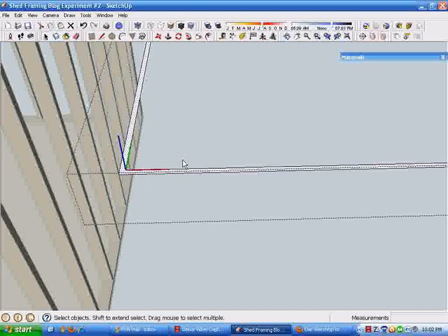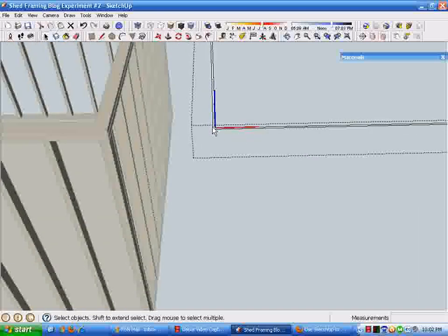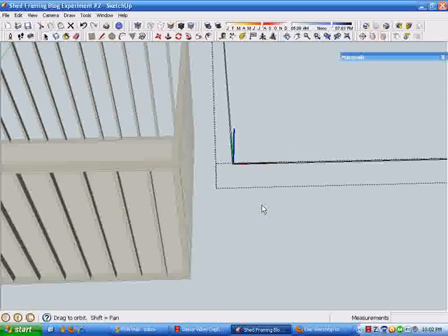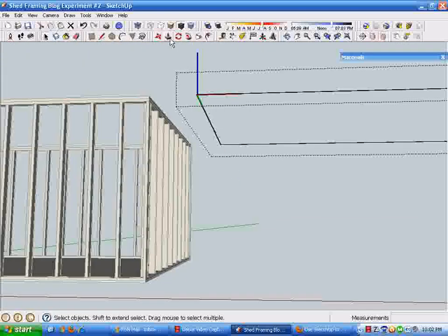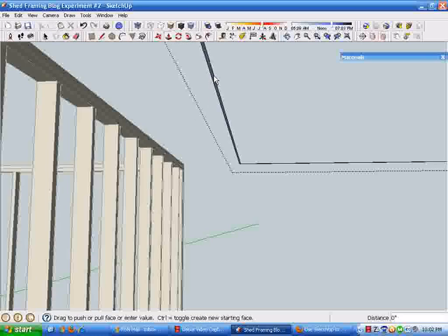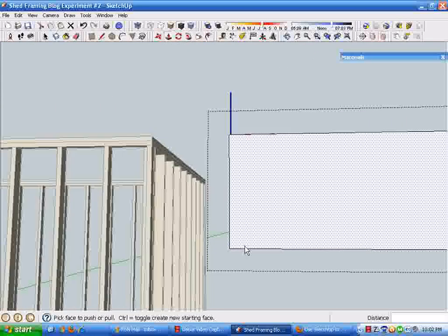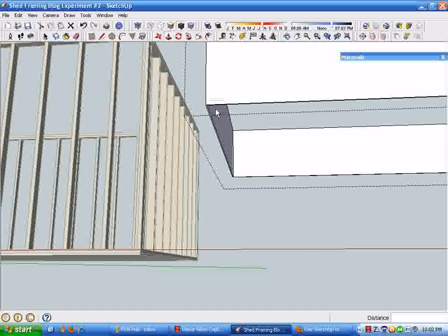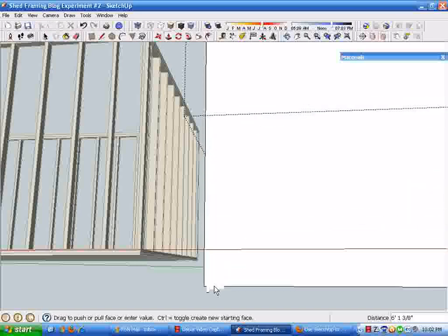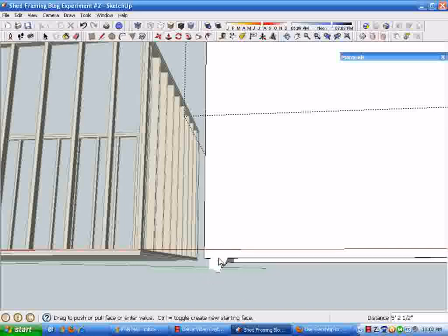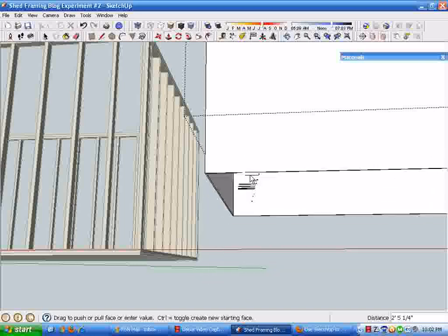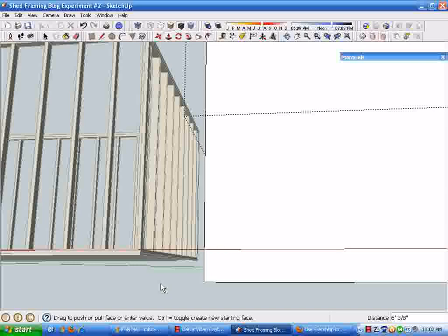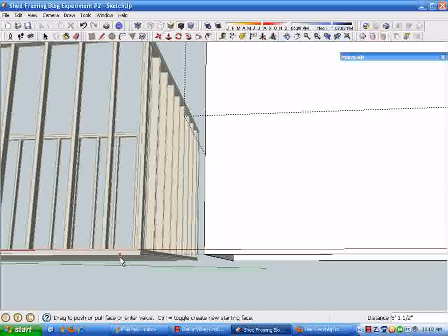and this rectangle on the same level as the top of our plates. So by rotating around, choosing the push-pull tool, dragging this surface, be careful to select the width. Now to get this the same height, I can dink around a lot here, or as long as I'm in the push-pull mode, I can hold down the Shift key and reference the bottom of this subfloor layer, and that'll make our sheathing the same height as our framed walls.